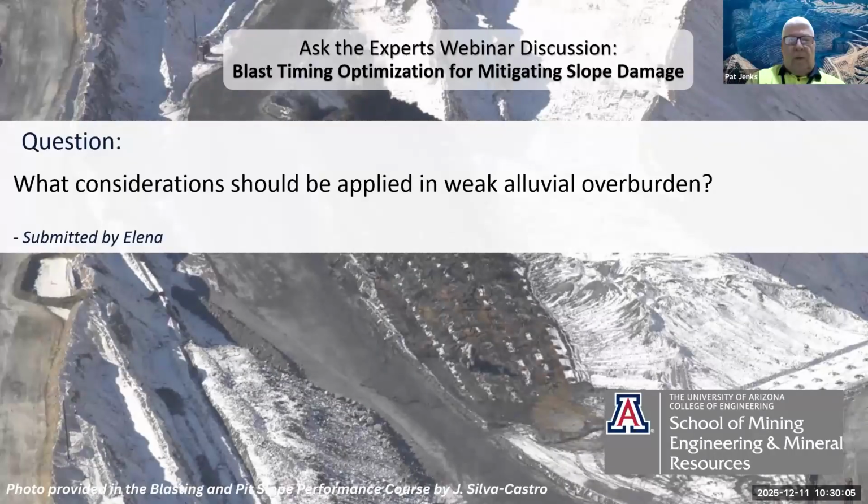Sure. I think this is a situation that's come up at a couple of our operations over the last several years, and a lot of it boils down to whether the weak alluvial overburden is cemented or not. Chris will reflect on this at Crossroads, when we're bringing down some of the waste and overburden material over the ore body. One of the things that we did is a lot of free digging within these alluvial materials, both with hydraulic and electric rope shovels. And I think that's a key thing to have a conversation with your operations team. Are the shovels capable of free digging in that material before you start shooting it?